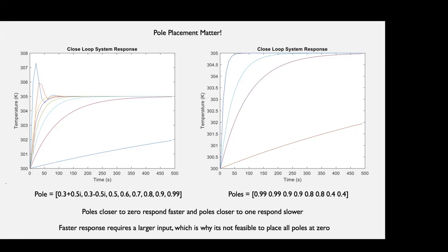To reiterate, the big key points are that you have your A matrix, which is your dynamics matrix, which has eigenvalues that tell you whether your system is stable or not. And then if your system is controllable, you can find an input gain matrix, K, to alter those eigenvalues to give you a desired response. So you could theoretically have an unstable system to start with that just does whatever. As long as it's controllable, you can find an input that will drive the system to what you want it to be. And that's pretty much state-based control for CubeSats.